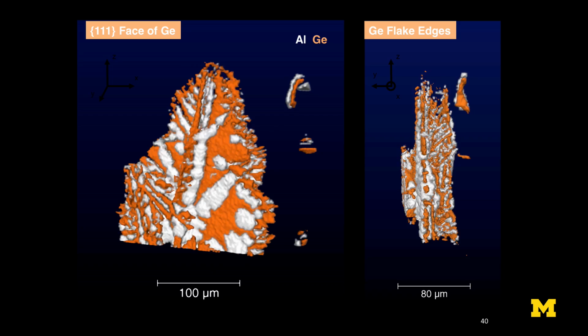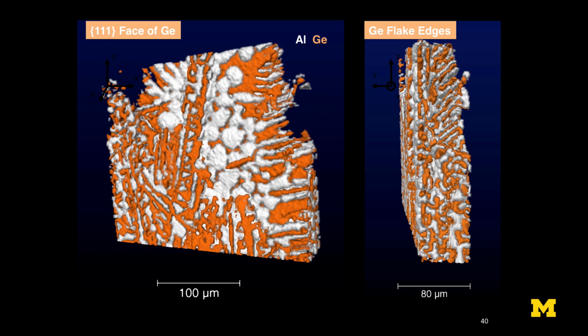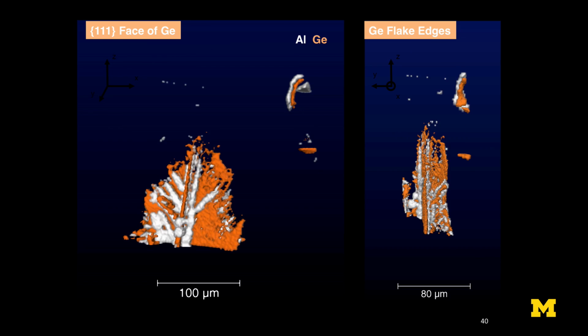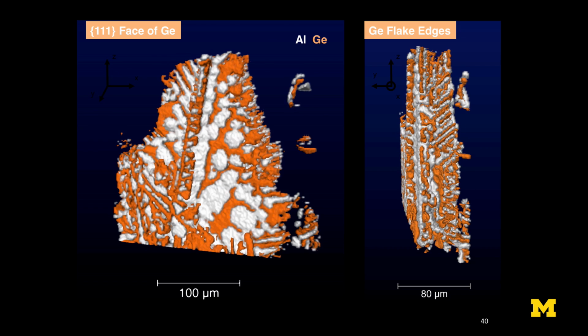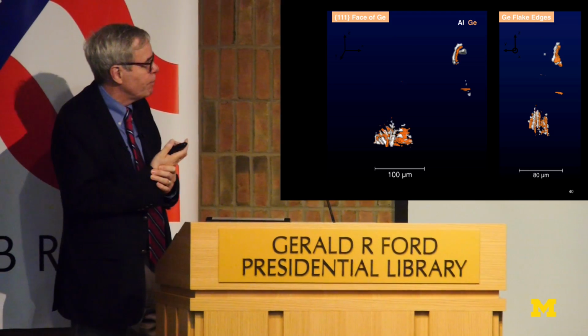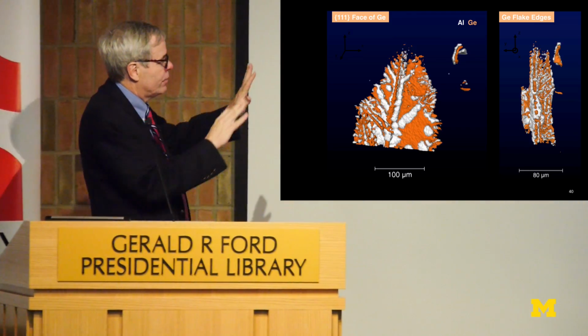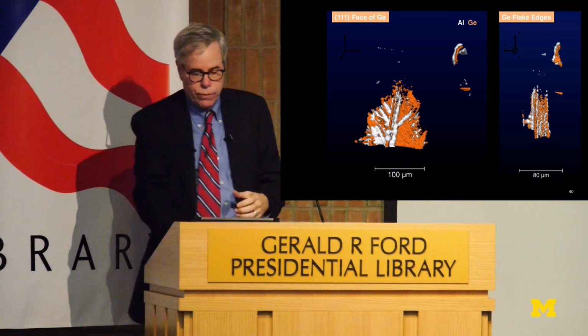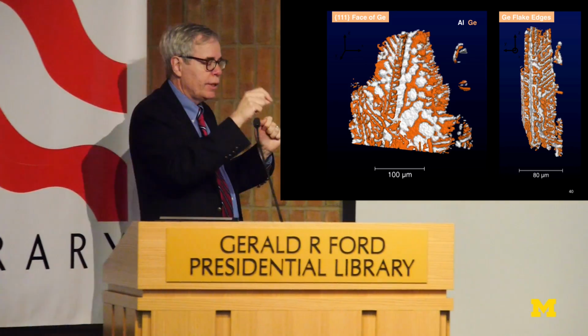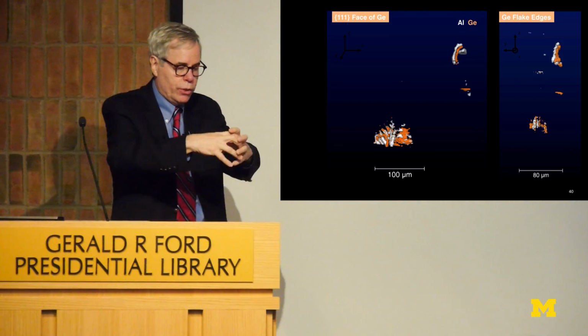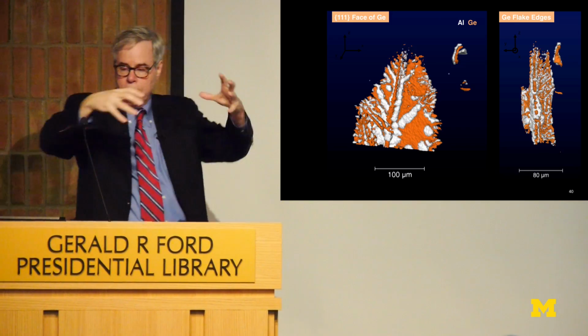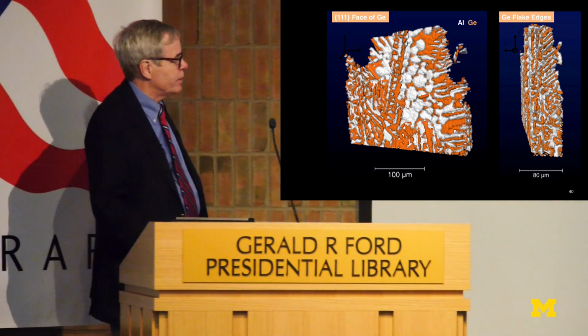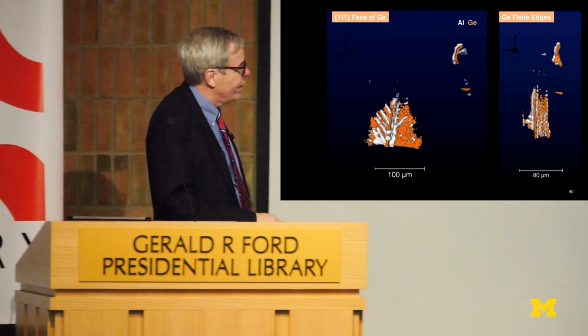And so we can now turn this on. So it grows up, and in about 100 seconds, occupies the whole frame. So the first general takeaway message here is, again, it's not growing like a snowball. If you nucleated an isotropic growing solid in a liquid, it would grow up like a spherical object. Here it's not growing like a spherical object. It's highly anisotropic.